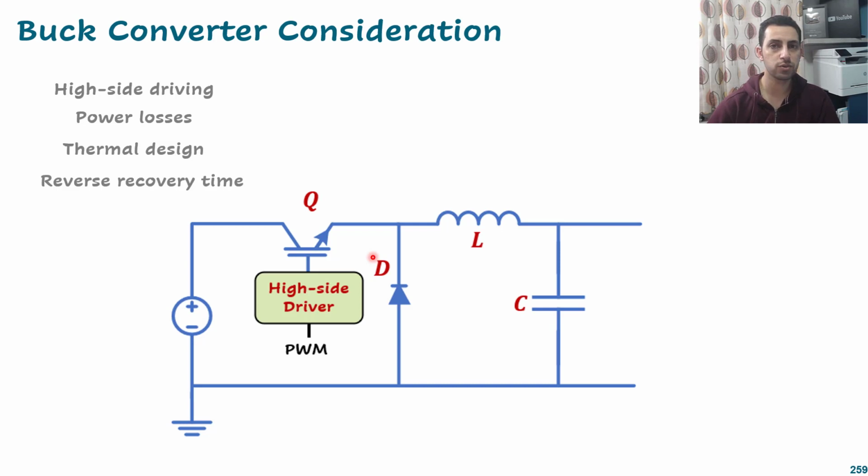But today I'm going to expand the talk to consider something related to the inductor and the capacitor. When I mean the inductor, I mean the inductor saturation. What we mean by inductor saturation, and why it's very important and might fail your buck converter if it's not considered well. And also the inductor ESR. ESR means the equivalent series resistance. So every component still has some very small resistance in series or in parallel. It depends on the component. And yeah, we have here the inductor ESR.